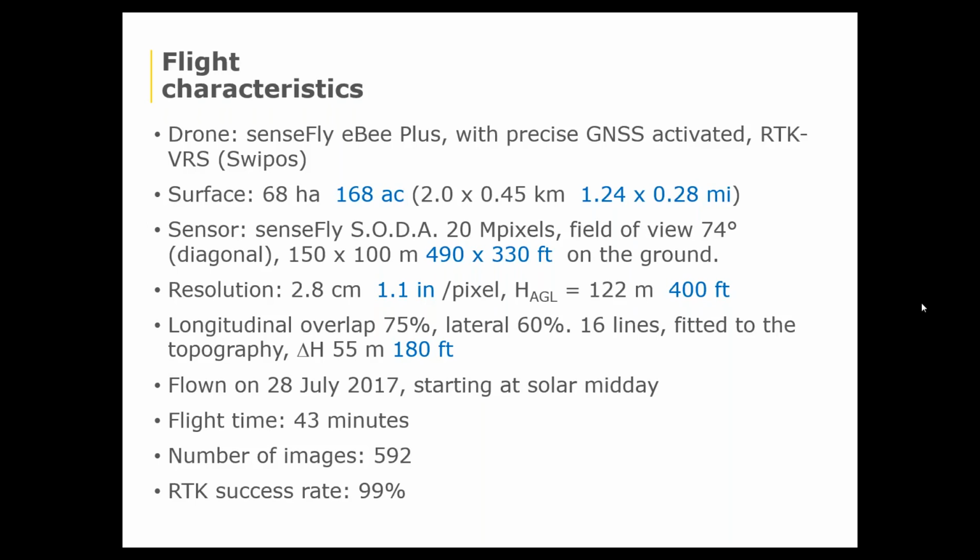The sensor used is a SenseFlight SODA, so this is 20 megapixel. And it makes a nice footprint of 150 meters by 100 meters on the ground. Resolution, we flew exactly at 400 feet, which means 122 meters, and we have a resolution of 2.8 centimeters, 1.1 inch, which is fantastic to see all kinds of details, and we will see plenty of them in the next slides and during the presentation later.